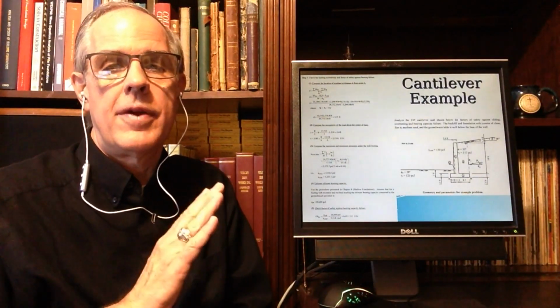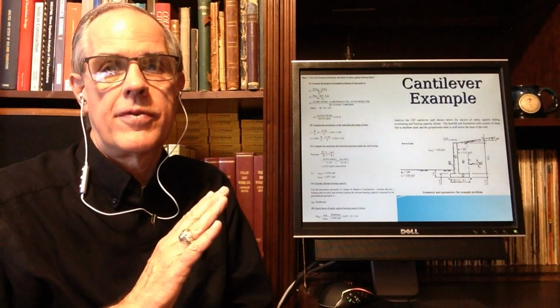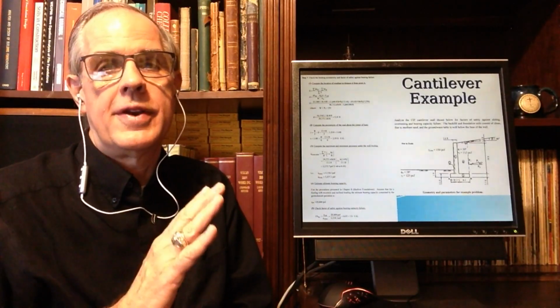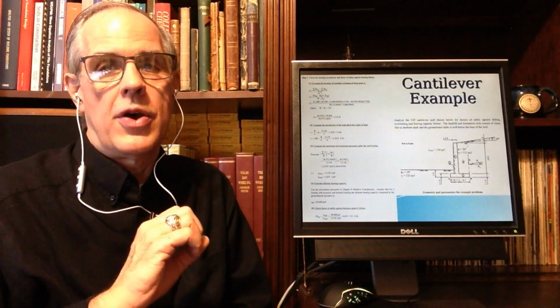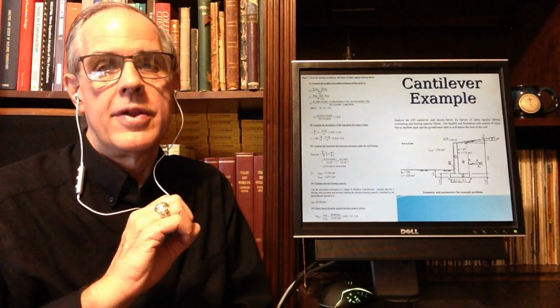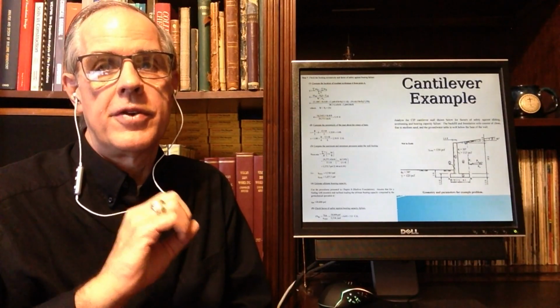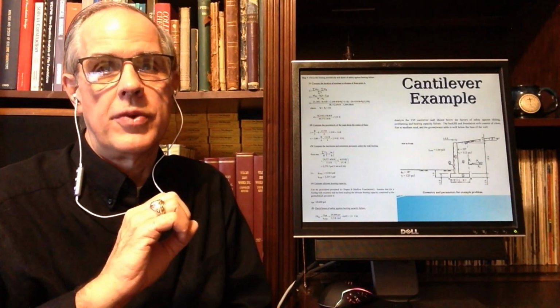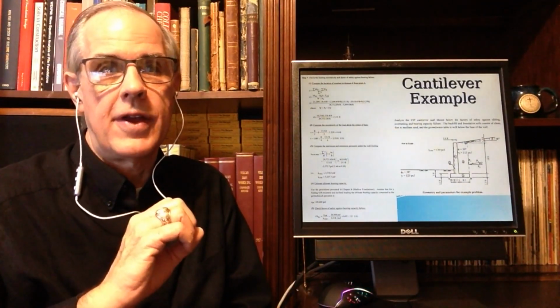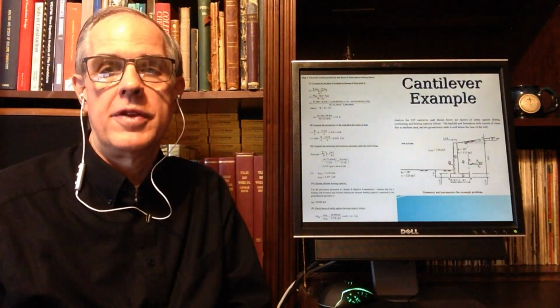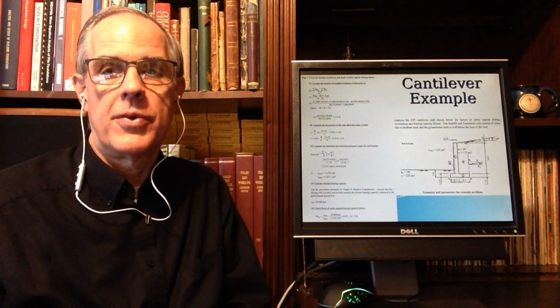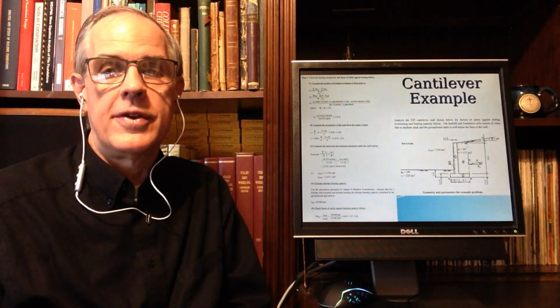You remember this from the middle third discussion we did with the bearing capacity analysis. What we want to know is whether the resultant vertical force on the base of the foundation is within the middle third. That's an additional check.